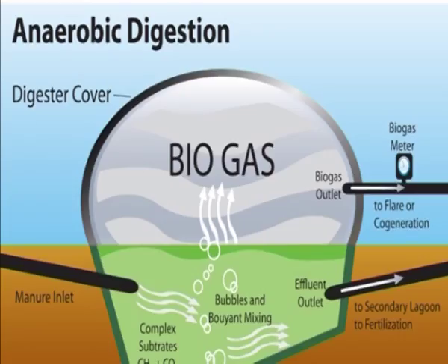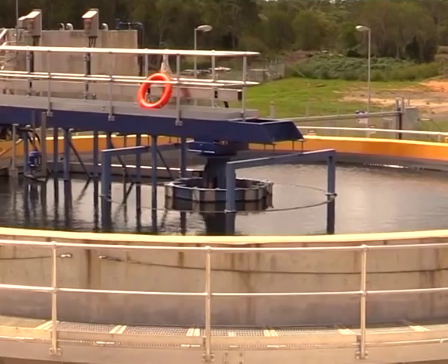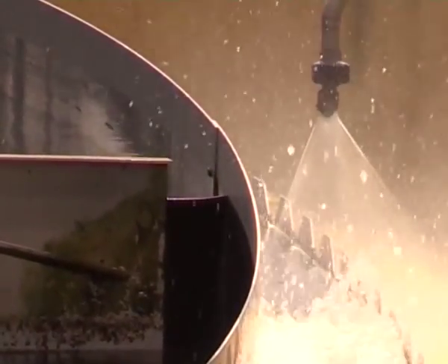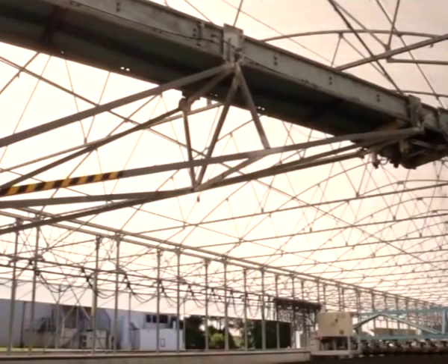In addition, anaerobic processes enable biogas production with associated energy recovery and are also characterized by low sludge production. Typical yields are less than 0.1 kg volatile solids per kilogram of COD removed.